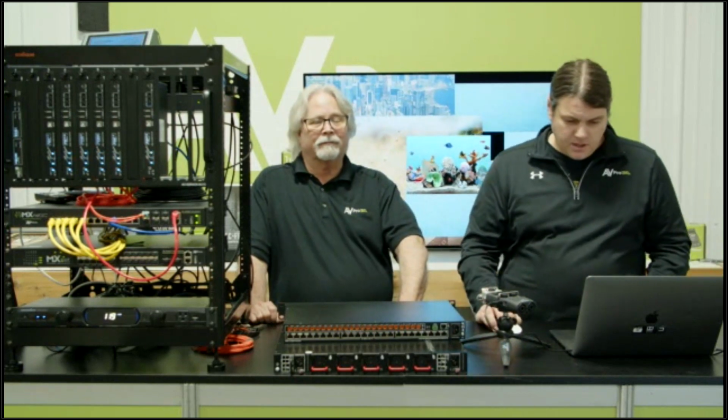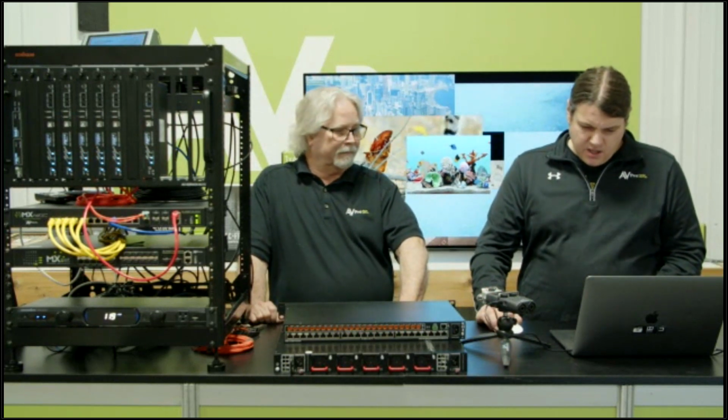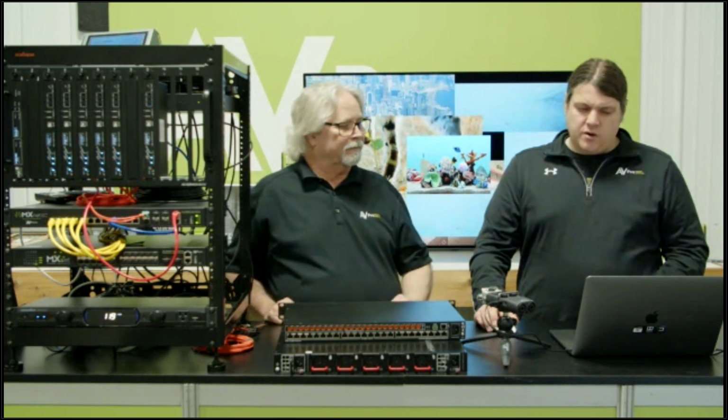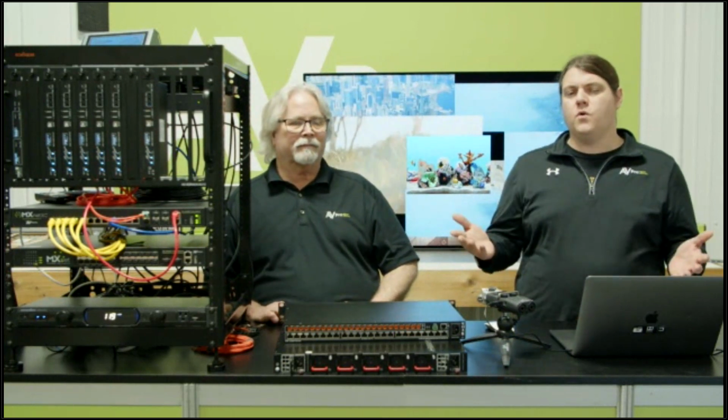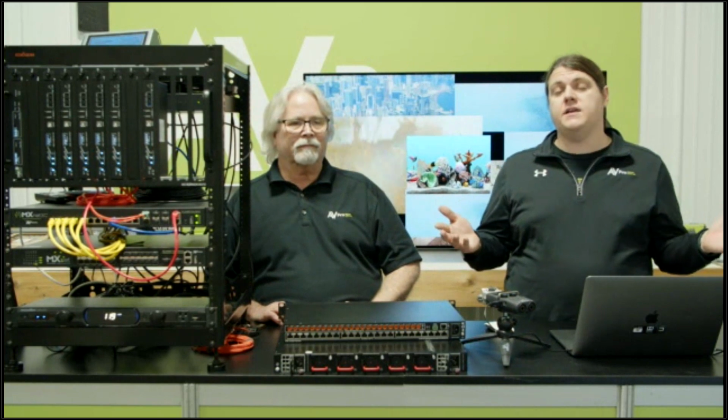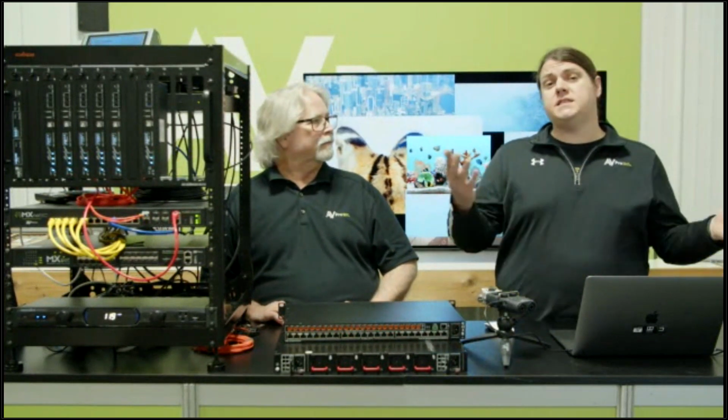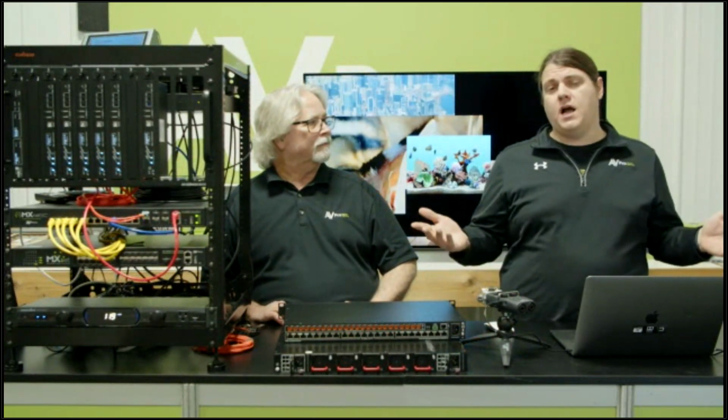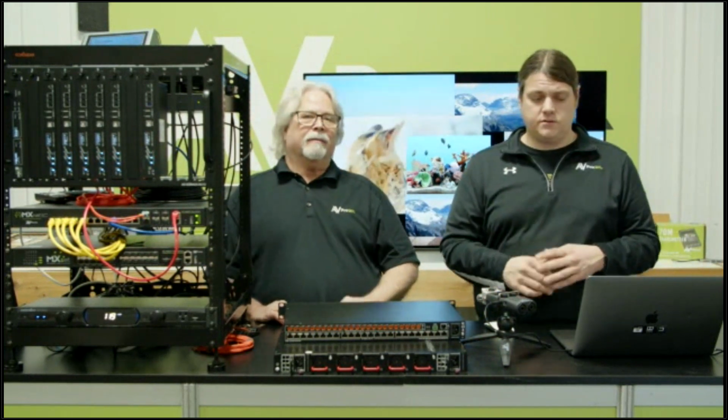All right, we have a question from Patrick. Wouldn't you have to compress an 18 gig signal? Yes, Patrick. Anything over 10 gig gets compressed down to 10 gig. So if you're doing a 4K 30 signal with HDR, that is sitting right at about 9.2 gigabits per second, which would be no compression. But let's say you're watching a 4K 60 football game on Amazon Prime. Well, that's going to be compressed down to 10 gig so that you can get your signaling. Great question. It's much lighter compression compared to the 1 gig system.